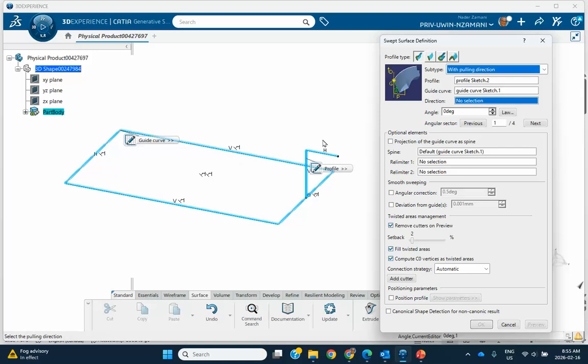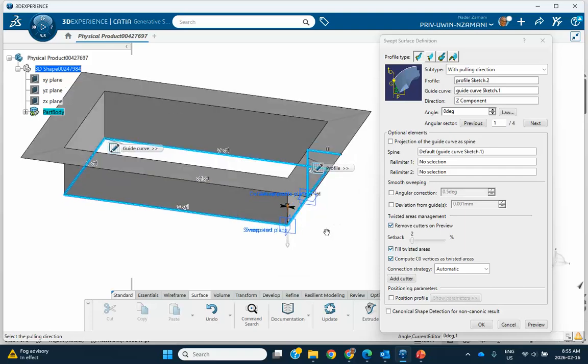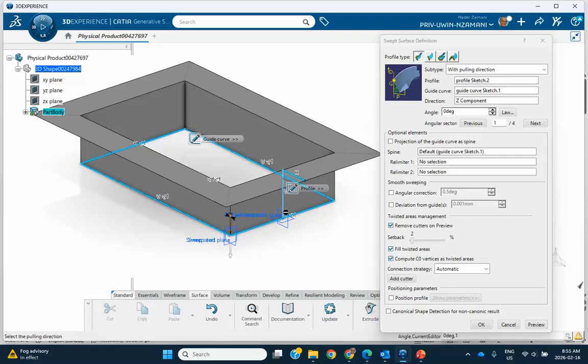Okay. Direction, let me make the vertical direction as the direction that I want, Z. So right click, Z. Okay. So Z is, see this arrow? Z is my direction. Now, notice that there is this option changing the angle. Right now, I'll leave it as 0. And I say preview. So when I preview, I get something like that. Okay, fine. That's a no-brainer because we take this inverted L and sweep it along that guide, you get something like that.